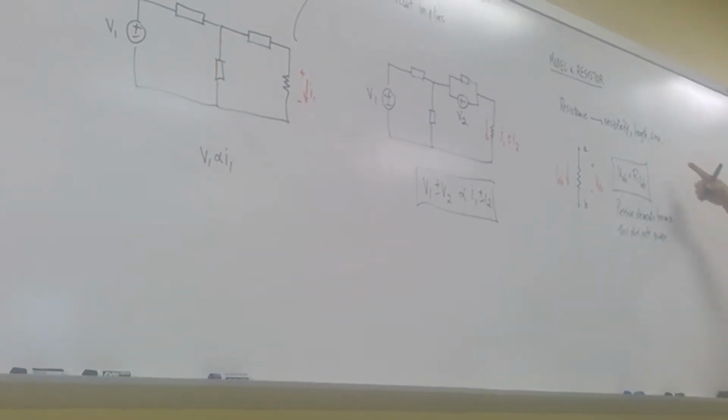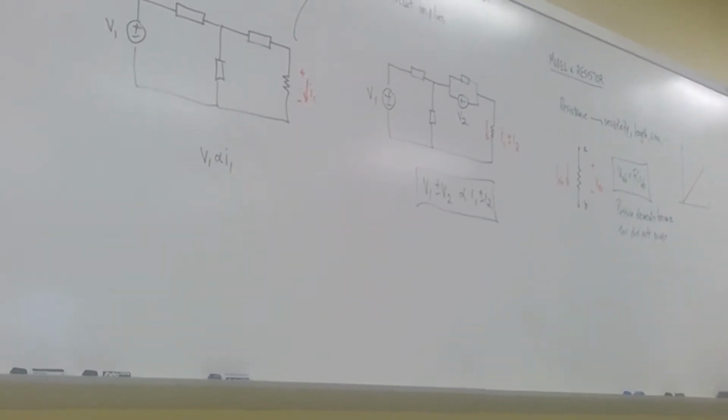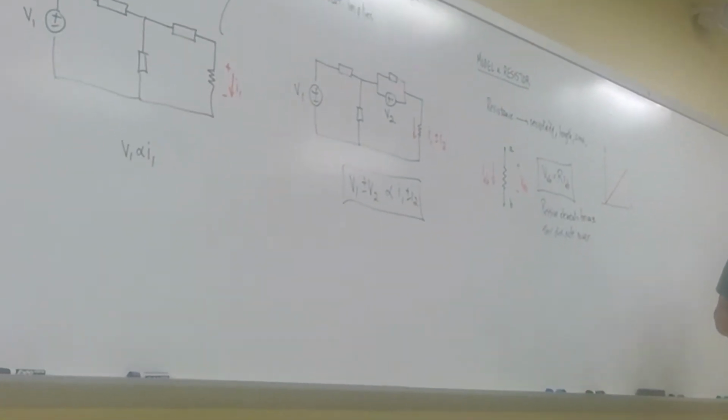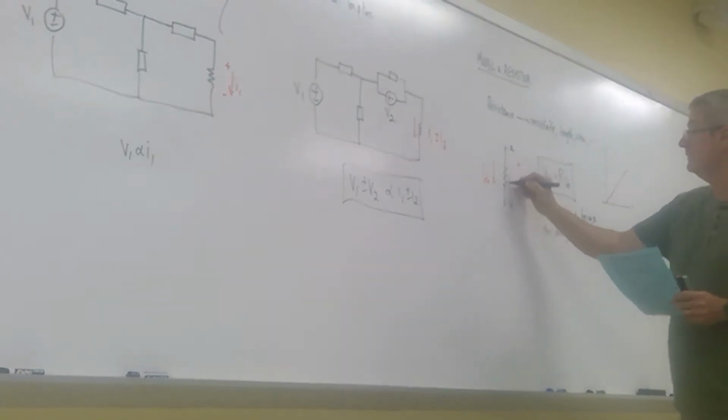And if I don't have much of a temperature change, I could plot voltage versus current, and I'll get what? I'll get that linear line. It's a linear element. That's what we mean by that. Are capacitors linear? No. Are inductors linear? No. Only when you get into AC do we start talking about capacitors and inductors being linear. So I typically don't write AB, I typically write the value of the resistor here. Maybe I should have put an R there.